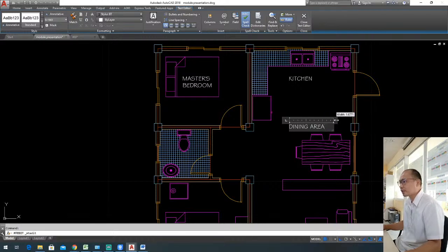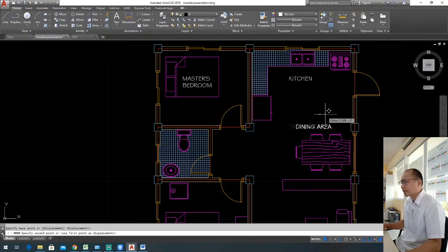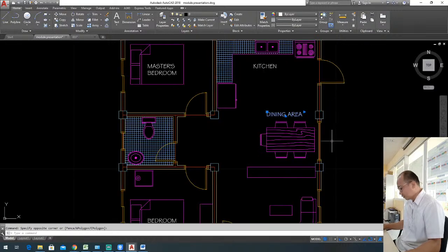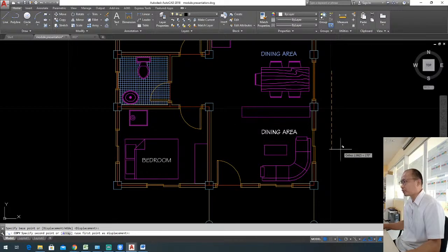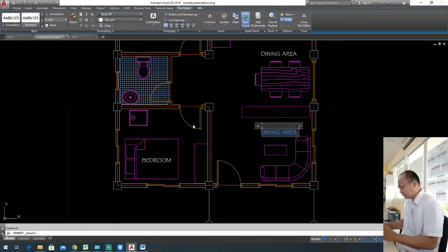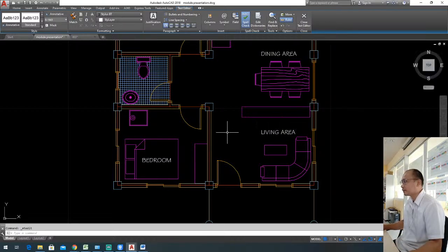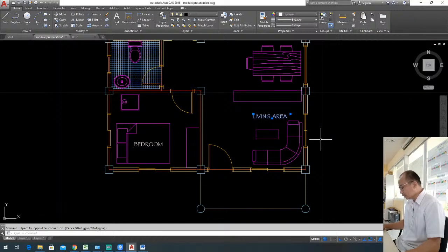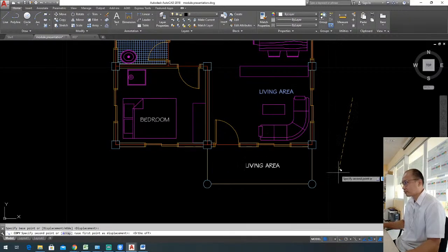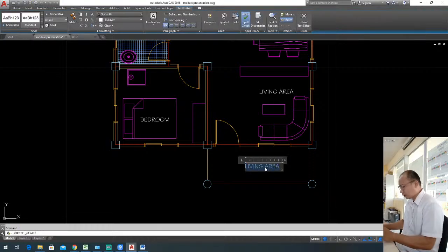All you gotta do is drag forward and backwards this transforming box right here, so you could easily drag it forward or backwards if you wanted to adjust the level of the text. Okay. Alright, so for example, I'm going to select the object and then copy that one, and then type living area. Okay. Then I'm going to copy, and then type porch.